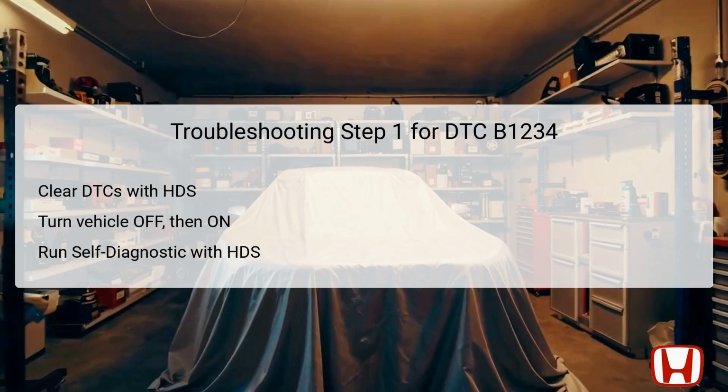Once the vehicle is in the on mode, it's crucial to perform the self-diagnostic function via the HDS or the climate control unit. This helps to accurately assess if DTC B1234 or DTC 41 reappears. If the code reappears, the failure has duplicated, prompting the technician to pursue further diagnostic steps to identify the exact failure point in the air mix control motor circuit.